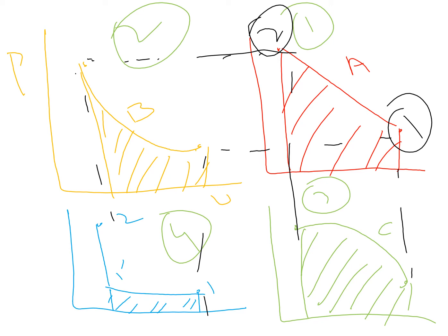So we will come to know that the work is path dependent, and the quantity of work we have to put in, or we will get out of the system, depends entirely on the behavior of the system, that is, how pressure is being changed with respect to volume. So this concludes that work for expanding boundary cases is path dependent, depending on the path that a system adopts to go from state 1 to state 2.